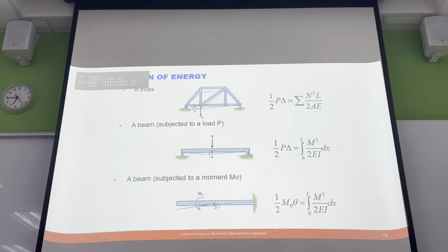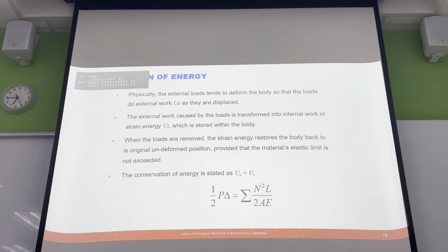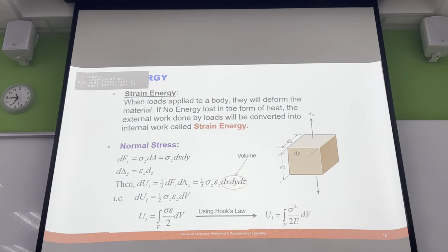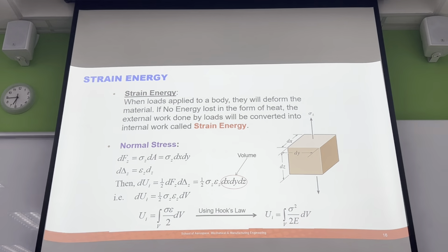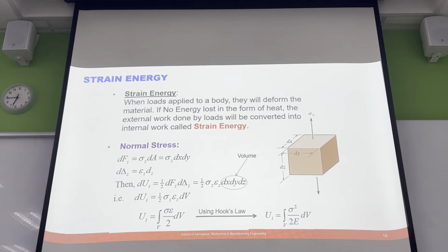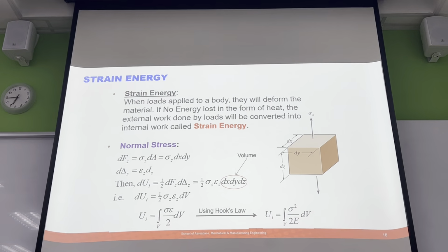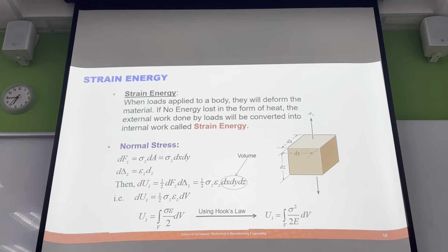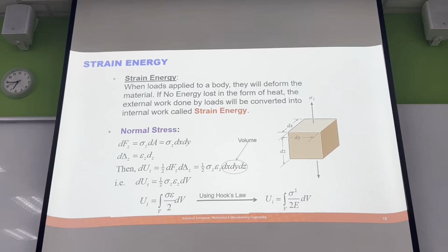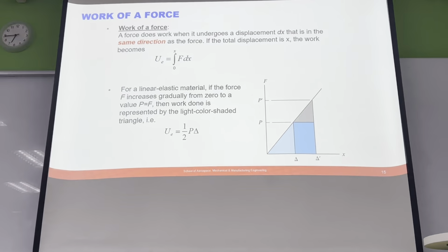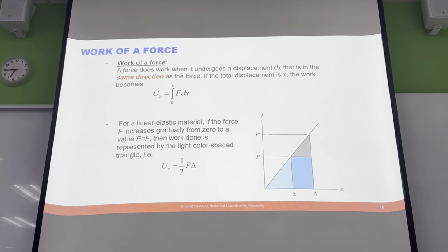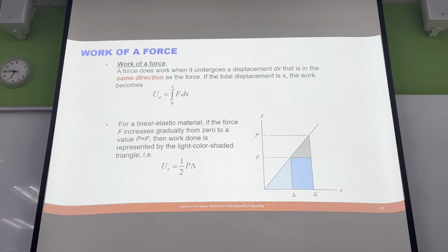So if you look back at where these came from, the fact that we could equate the strain energy. We also use the stress. If we have a formula which tells us the stress throughout the volume due to a particular loading, that is the strain energy, and that is equal to the input energy.